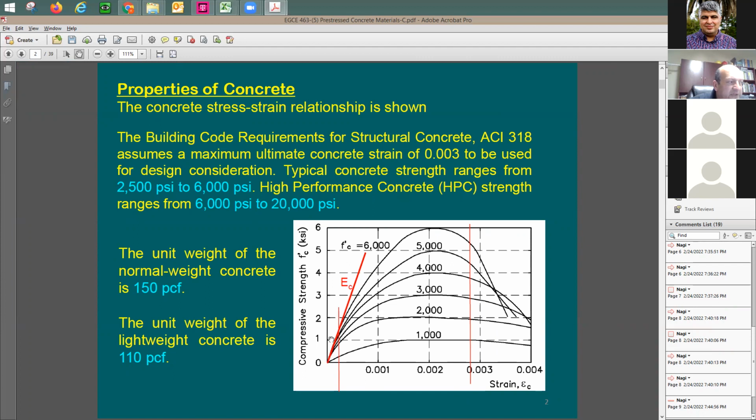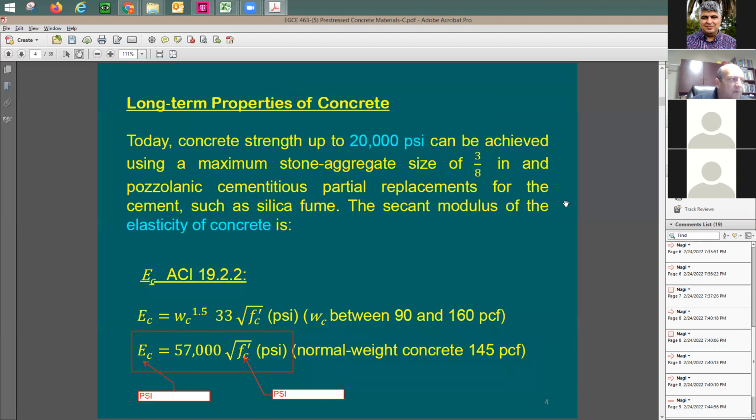So maybe the first amount of strain that you called elastic, you can recover back. But the rest of the strain, from here to there, you cannot really recover back. And it's going to happen instantaneously. You don't really need to wait. This is regardless of the creep phenomenon at all.